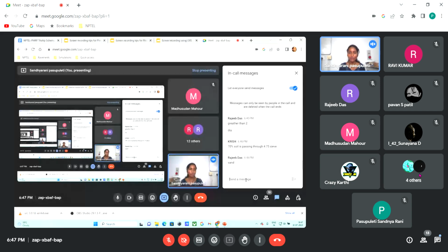So any soil size that is greater than 75 micron is a kind of coarse grained soil. So if I take the 4.75 sieve, if the soil amount is more than 50% is retained on 4.75, we call that as gravel. If more than 50% is retained on 75 micron, that we call as sand. So based upon these two criteria, first we have to determine whether the given soil is sand or gravel. Okay.